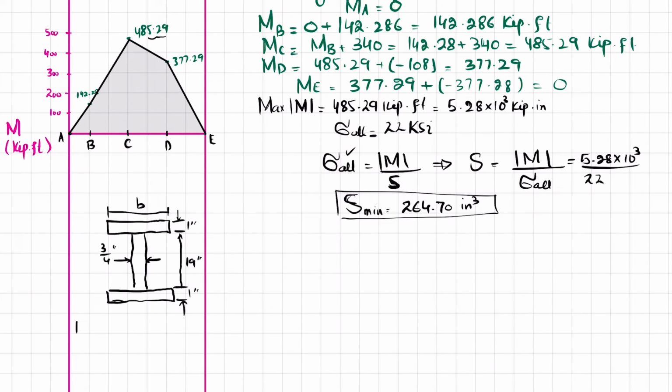So we have to calculate the moment of inertia for this. As we know, moment of inertia I is equal to, now you can see that we have three plates: this is one, the second is this, and the third is this. If I draw the centroidal axis, it will be at the half. So we have I2 plus 2 times I1, because I1 is equal to I3. What is I2?